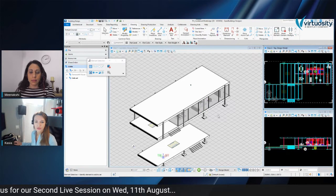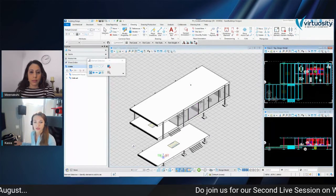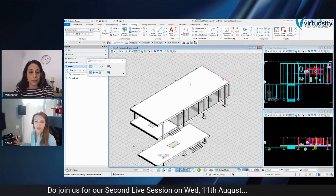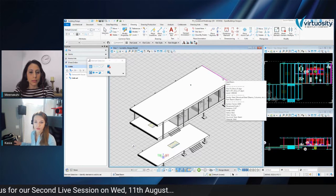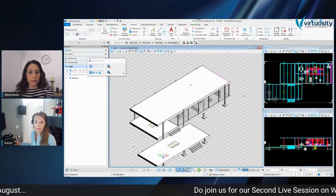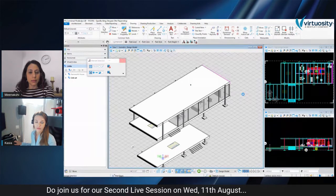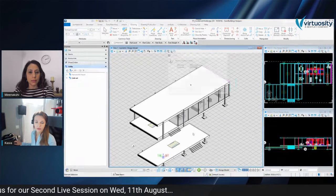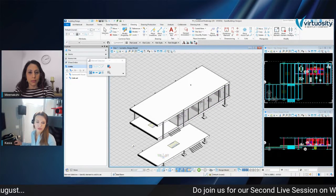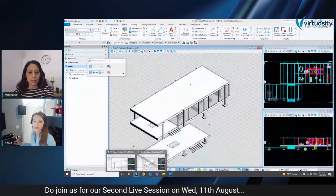That's how it makes the cooperation easier. Of course, also being the project manager, I can change something in the master file. All I need to do is activate the references for the moment. So for example, with the right click, I can activate one of the disciplines, and it will simply become an active file for a moment, the working model, and it will deactivate other references. And then if I make a change, again, it will work the same. It will get updated in other files. So for example, for the structural designer.